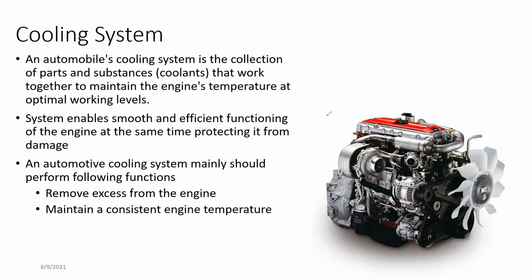If they continue to work at this temperature without adequate cooling, the metal components, that means the cylinders and piston rings, will expand. That expansion will exceed the limit the components can withstand, which results in the engine getting stuck, or what we call a seized engine.